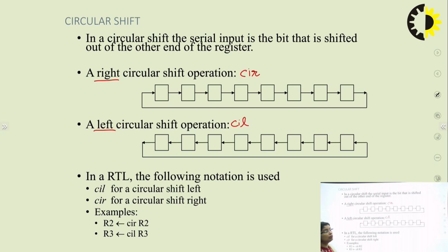In the logical shift micro operations, bits were lost, either at the MSB or the LSB side, because these 2 bit values are lost. These bits cannot be lost with the circular shift micro operation. In the circular shift, you are shifting the position of the bits, but no bits are lost.